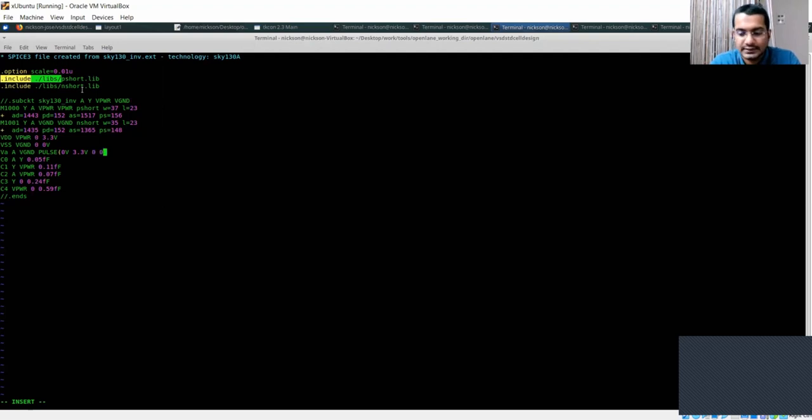The rise time is 0.1 nanosecond, 0.1 nanosecond the fall time. This 2 nanosecond is the on pulse width, and 4 nanosecond is the time period. So this is how we define a pulse in the SPICE deck, and post that we will also include the type of analysis which we want to do.